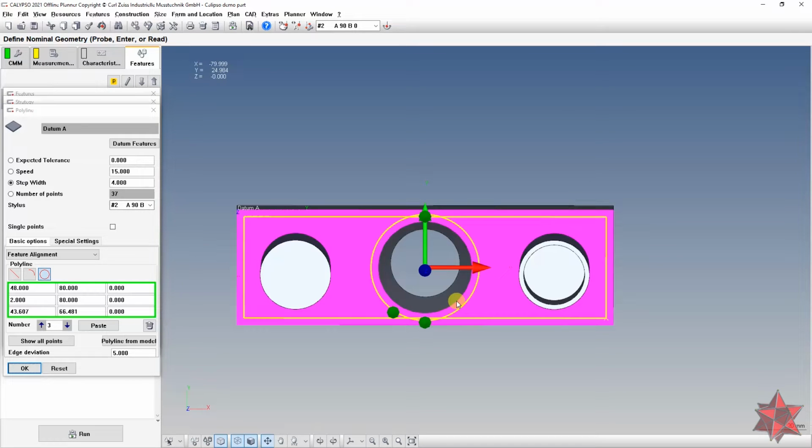Here it says that if we have a plane with the size from 81 to 250 millimeters, or 3.1 to 10 inches, we can use a speed of 10 millimeters because I'm using a passive sensor, right? So I will use a speed of 10 millimeters for a passive sensor, and a step of 0.31 millimeters, and we will generate 467 points scanned for all of the plane.